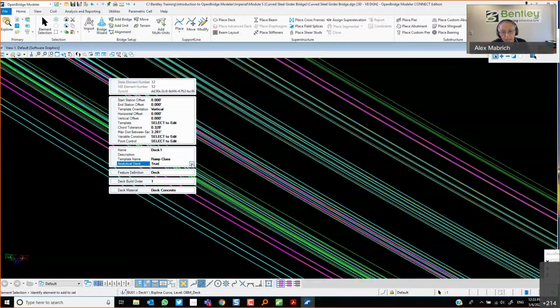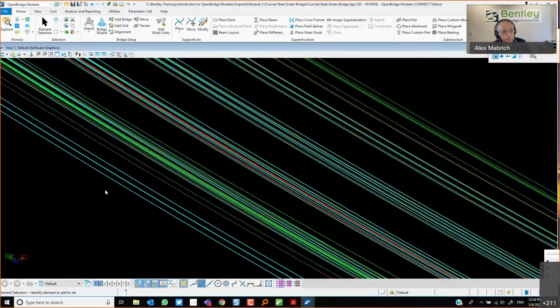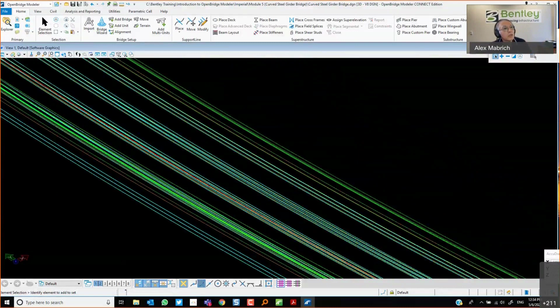And in Leap, as being analytical, it doesn't consider that wearing surface deck that you place. You've got to enter manually the load that is getting into that, right? But that would be maybe the workaround to place a deck on top of a deck. And sometimes this is the same workaround that people use to place median sidewalks, to place sidewalks, right? Sidewalks could be placed as a barrier element, but also could be placed as a limited deck option too, right? So many options right there. So let's see.